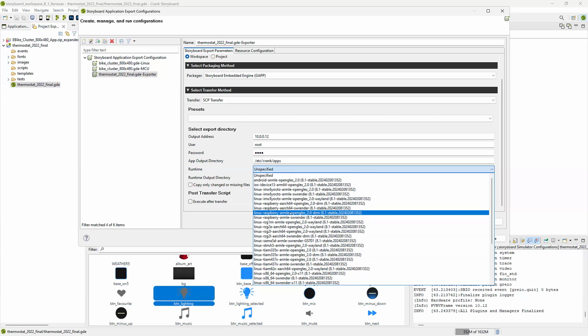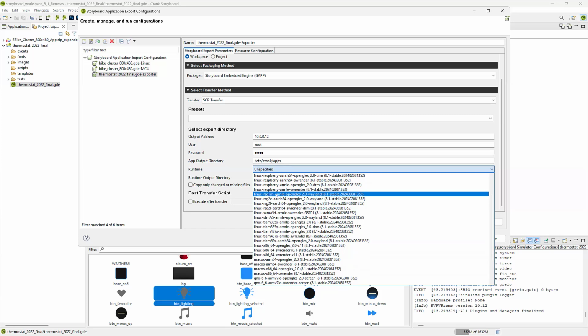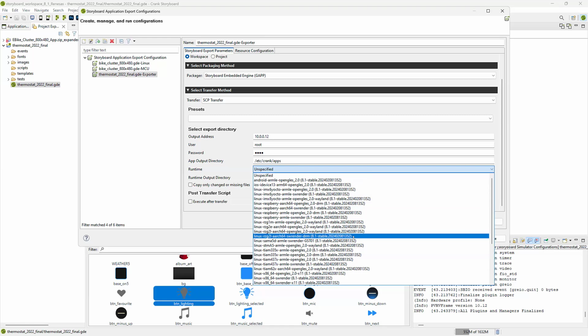From the hardware up, we use a specific target hardware for the target board. In this case, we've got ROMs pre-arranged, and as soon as we get hold of the RZV2, we'll be able to give you a runtime for that. There are different flavors: a G2L with software rendering and DRM, and ones with hardware acceleration using the Wayland OpenGL ES 2 drivers, and we can create and optimize these for whichever platform we need. This isn't all that we do. We have a great many more, but if we included every one of these in the install, it'd be gigantic. So we don't do that.